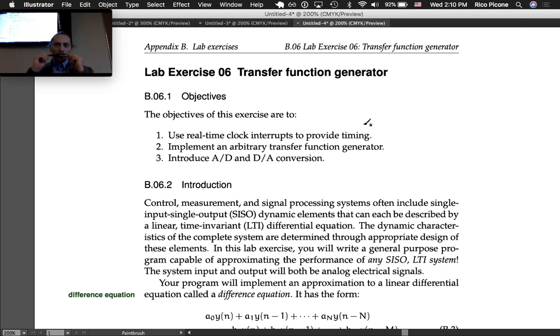It's better. When we do it like that, it means that this is periodic, and we can predict the time of the interrupt. As long as what we do in the meantime doesn't overfill the time that we give ourselves with the interrupt, we'll be fine.